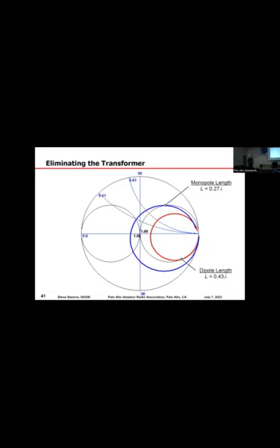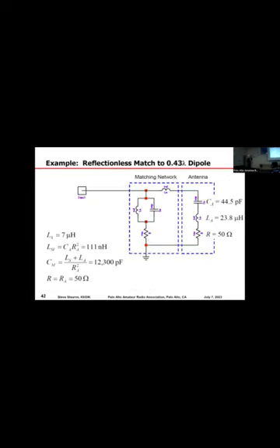So let's go to the next slide. In the case of the dipole, I'm going to add a series resistance to cancel out the reactance at the design frequency.